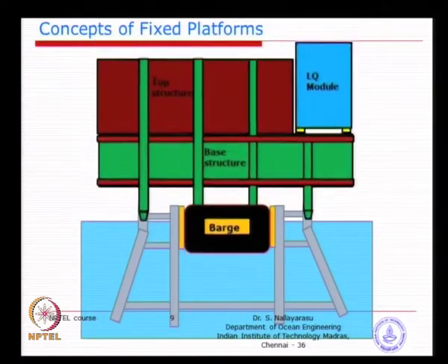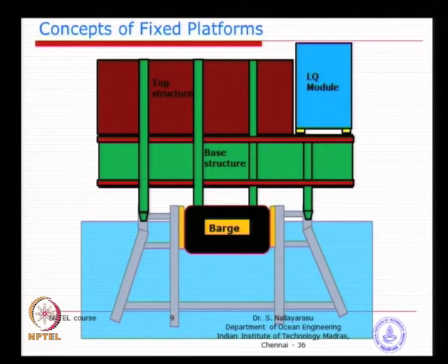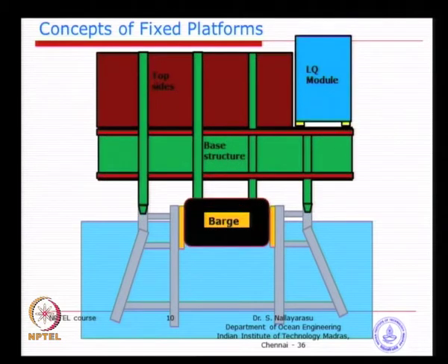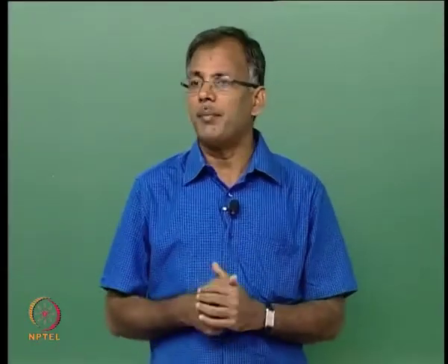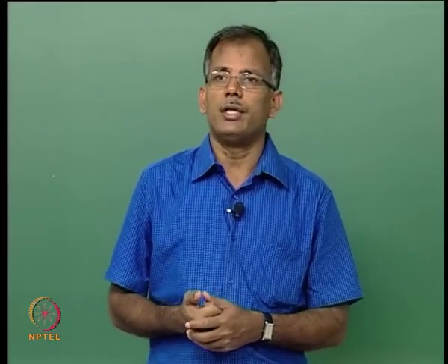Basically you see here in this animation, the barge is coming in elevated by, say, 1 meter, which is a typical number, and then comes into the slot. Yesterday you have seen the video. So, basically there will be a minimum gap maintained. The gap is to make sure that accidental impact does not happen.